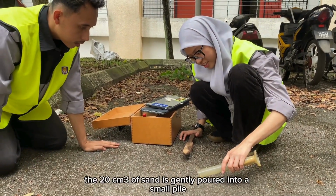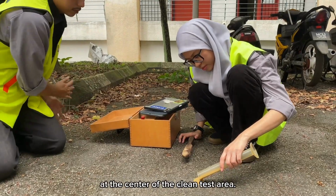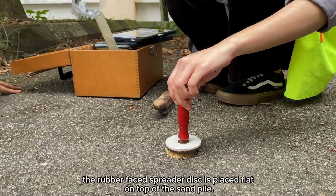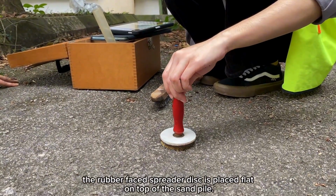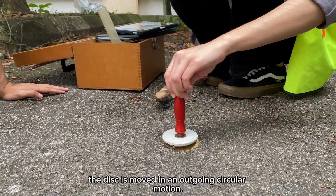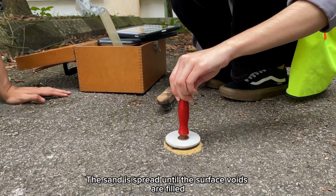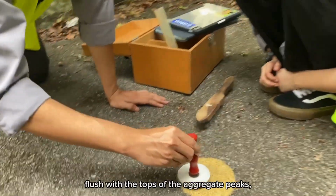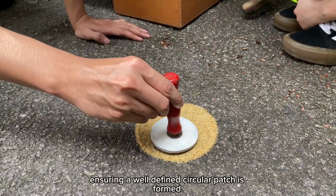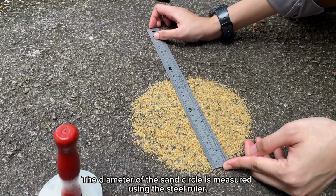Third, the 20 cm cube of sand is gently poured into a small pile at the center of the clean test area. Then, the rubber faced spreader disc is placed flat on top of the sand pile. Using light, uniform downward pressure, the disc is moved in an outward circular motion. The sand is spread until the surface voids are filled flush with the tops of the aggregate peaks, ensuring a well-defined circular patch is formed. The diameter of the sand circle is measured using the steel ruler.